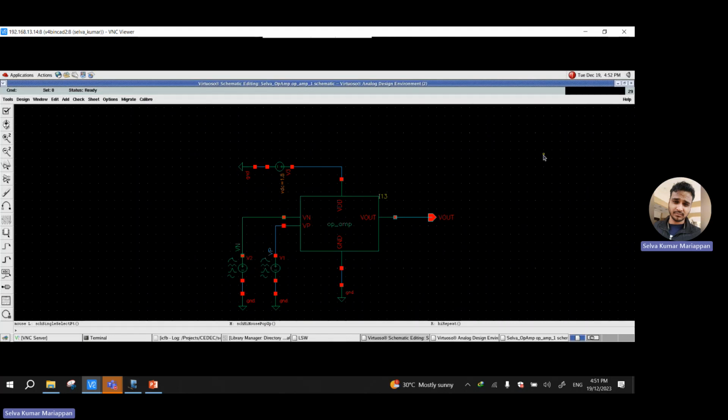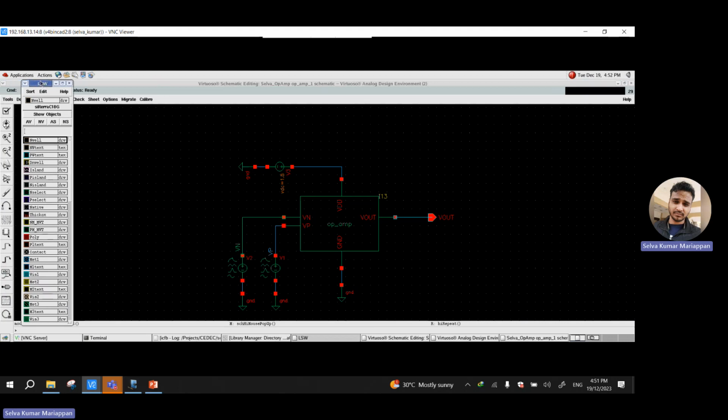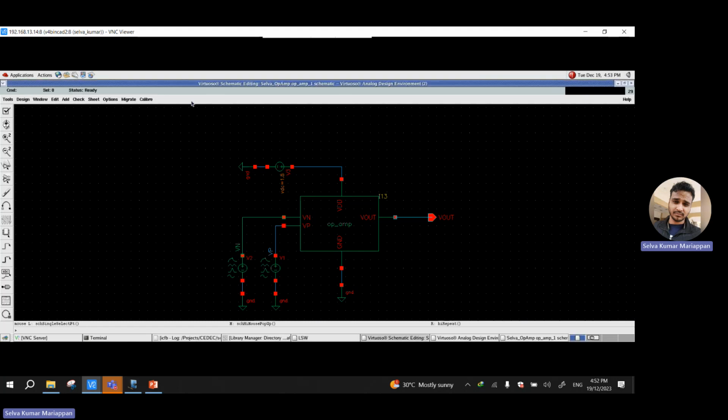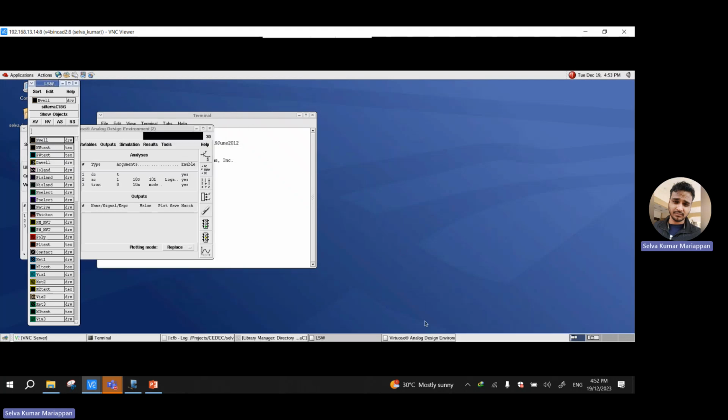One of the bugs that I want to insist on here is this layer window. Once you open your layout, this thing you cannot close, so it will just be there. In order to get rid of it, you have to close everything and start again. So I'm going to close everything. For you, no need, because you never opened the layout yet. I already opened it, and I just cannot get this to disappear. So I need to close everything here.